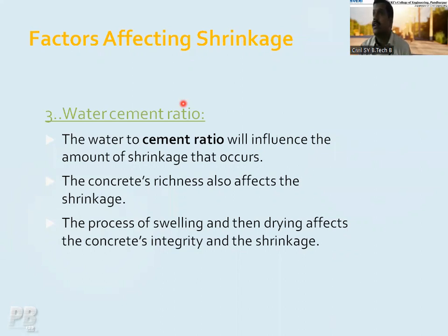The next factor is the water to cement ratio, a factor which is going to affect the shrinkage. The water to cement ratio will influence the amount of shrinkage that occurs. The concrete's richness also affects shrinkage. The process of swelling and then drying affects the concrete integrity and the shrinkage. How is the water cement ratio playing a role in the shrinkage?